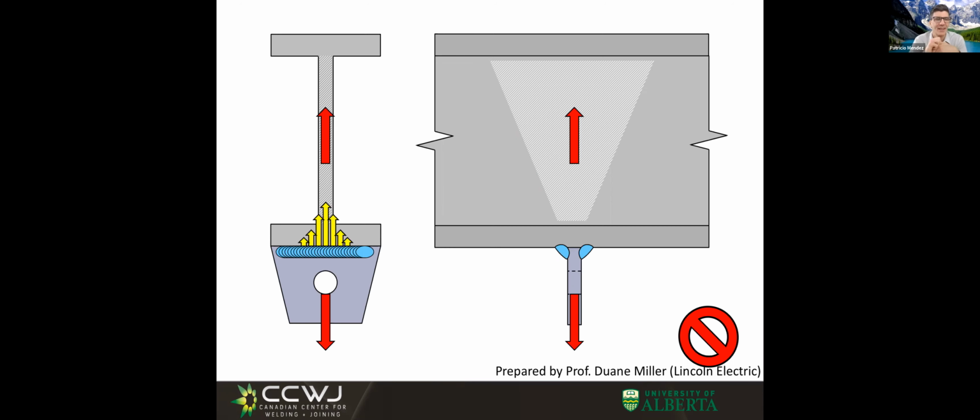I will tell you. What happens is that this part of the weld is pulling on something very stiff. That is the flange. The load is transferred to the web here, but here in the flange there is compliance, right? If I were strong enough and I pushed up and down on the flange, I would be bending the flange. Now, if I push up and down on the web, it doesn't move all that much, right? I have all this enormous section blocking me.